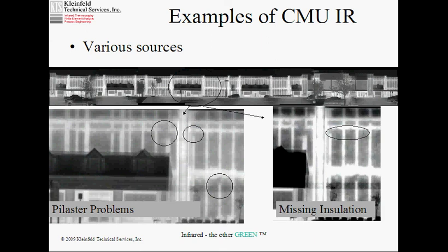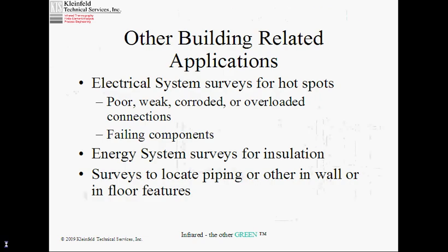On this other image, which is harder to see and harder to reach, can you see that there's a slight difference in the color here, here, and here than the areas immediately next to them? Is that visible? All right, and that's the insulation or lack of insulation in the non-pilaster, non-grouted, but allegedly insulated cells.